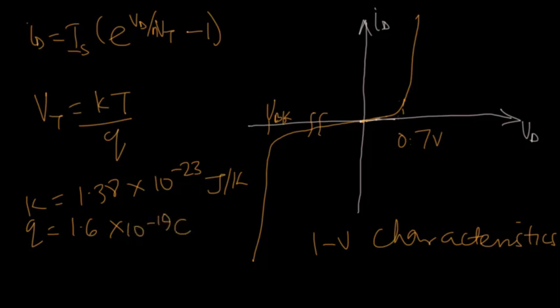And then you have temperature T in Kelvin. At room temperature, V thermal is 25.3 millivolts, and that's approximately equal to 25 millivolts. So if V thermal is not given and you are told that it is at room temperature, you can either use 25.3 millivolts in your calculations or 25 millivolts.